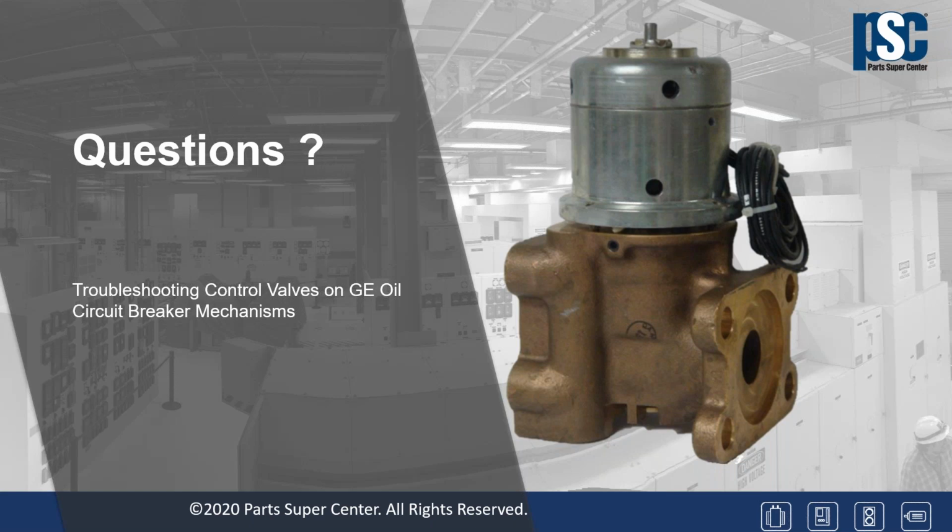And then finally, the valve housings are hydrostatically tested after they're machined once they come out of the foundry. So we have a test fixture that will generate the appropriate working pressure, maximum allowable working pressure, and we make sure that there's no leaks on the valves since they are a pressure vessel.